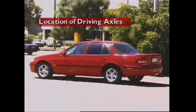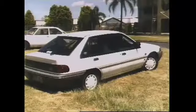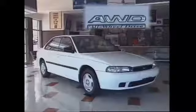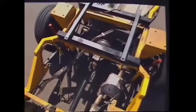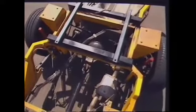The location of the driving axle determines whether the vehicle is classified as rear-wheel drive, front-wheel drive, 4-wheel drive, or all-wheel drive. Rear-wheel drive vehicles can use a conventional layout with the engine at the front of the vehicle. The torque from the engine is transmitted to the rear-mounted driving axle by propeller or drive shaft. This spreads the weight of components throughout the vehicle.